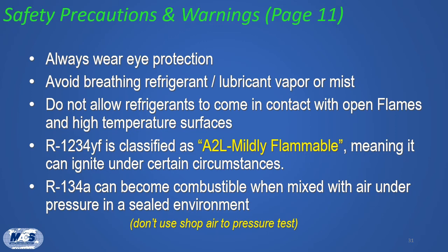Now, R134A we think of as non-flammable, but it can actually become combustible when it's mixed with air under pressure in a sealed environment. So we want to make sure everyone knows to not use shop air to pressure test an R134A system.